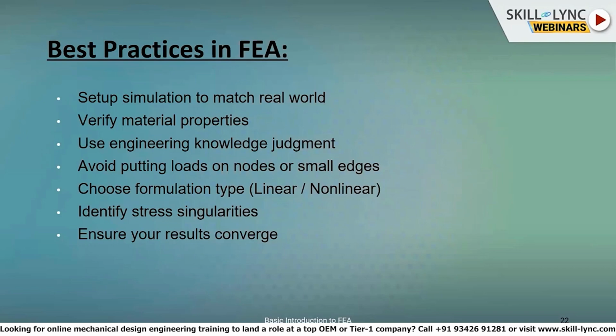Then choose formulation type, that is linear element or quadrilateral element. That is the meaning of that. Quadrilateral elements will give good results, but it also depends on analysis to analysis.